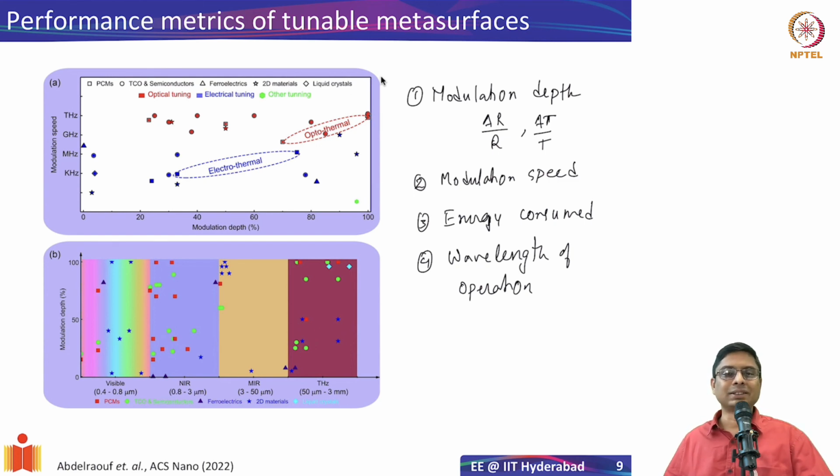It looks like liquid crystals are not really that easy to manage because of other issues like they tend to aggregate near the surfaces and so on. Phase change materials are good, and semiconductors are also good if you can modulate them. The semiconductors also have this additional advantage of being compatible with the existing fabrication technology. And we can have carrier injection, or carrier movement, which is very well understood in semiconductors. So this is what I wanted to tell you about tunable metasurfaces.